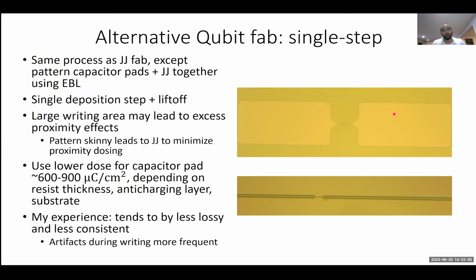But there are others in our group that do wire bonding for, say, parametric amplifiers and stuff like that. And I believe the big precaution that you take is to make sure you have one of those ESD bracelets, and make sure that you yourself are grounded and you're not generating any excess electrostatic discharge. And make sure your bonder is grounded as well.